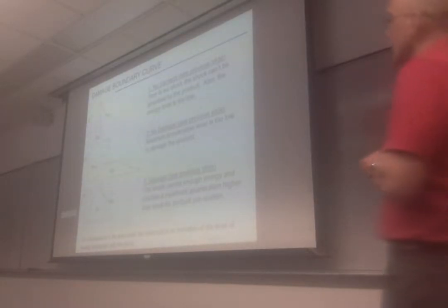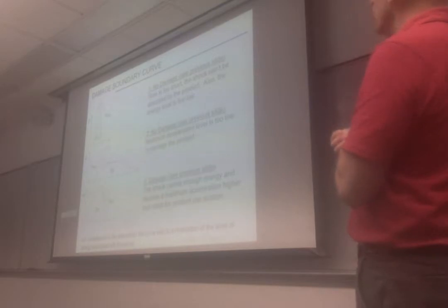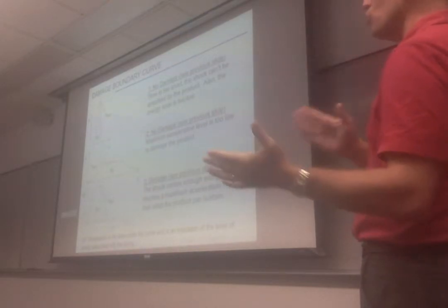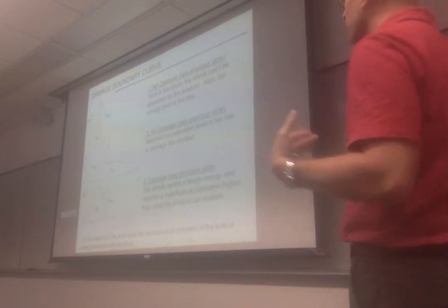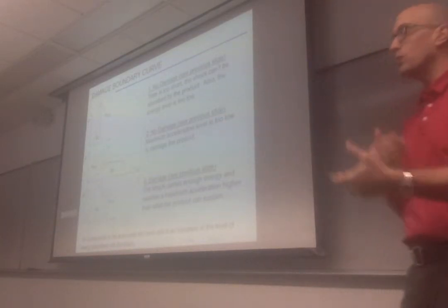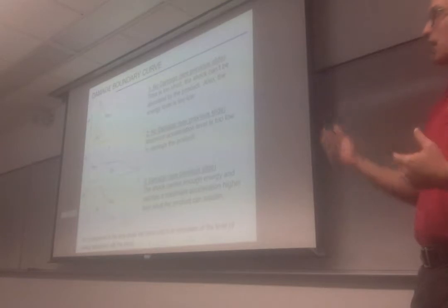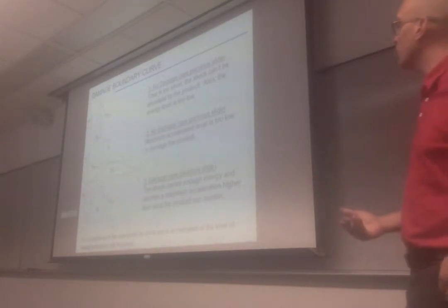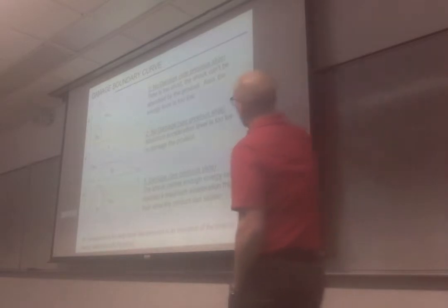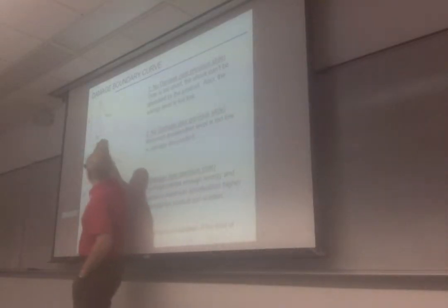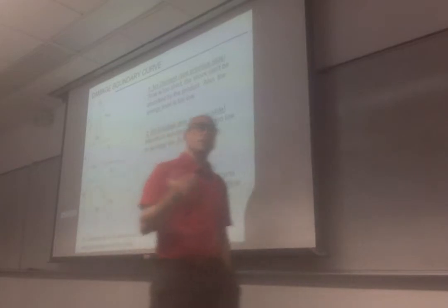In this case, you have no damage because the time is too short. The shock can't be absorbed by the product. It has to do with the frequency: it's such a high frequency that it's not very well transmitted to the product. Also, because there's very little area under this, even though there's high acceleration, there's very little energy in that impact, because the area under the curve, which corresponds to velocity change, also corresponds to the energy level of that shock. Does it make sense?